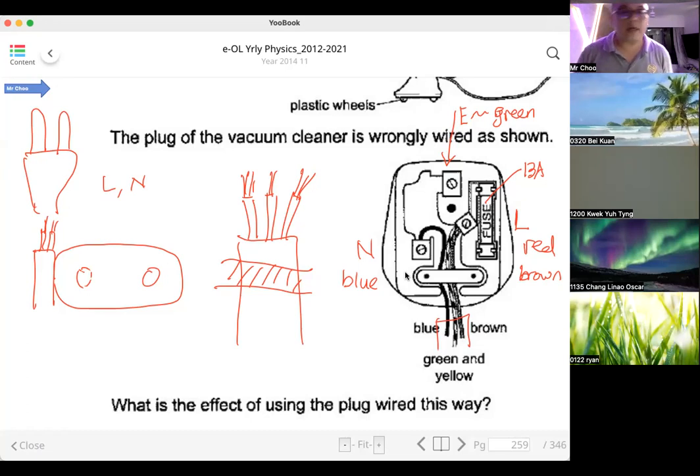The skillful thing that you might need to possess is practicing how to strip the edge of the insulator out so that you can screw in properly. That is the part that needs a bit of experience and skill. After someone teaches you 1 or 2 times, it should be quite easy. Because if you use a scissors and cut all the way, the whole thing gets cut. So you must know how to cut halfway, then you strip away the insulator without cutting the copper wire.